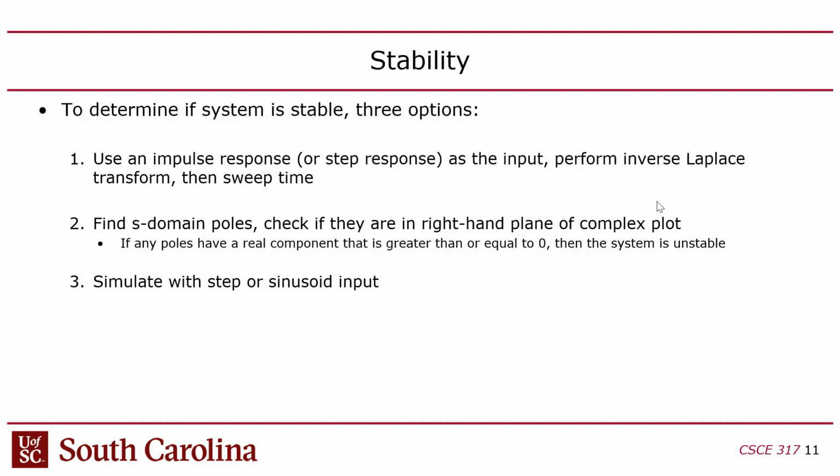And when it comes to systems that are unstable, generally speaking, they're not unstable for any input. They're only unstable under certain frequencies of input. And so by doing an impulse or a step, you're essentially exposing the system you're testing to an infinite number of frequencies, like every frequency, right? And so if it is unstable in response to any frequency, then it is guaranteed to become unstable after having experienced an impulse or a step, right?